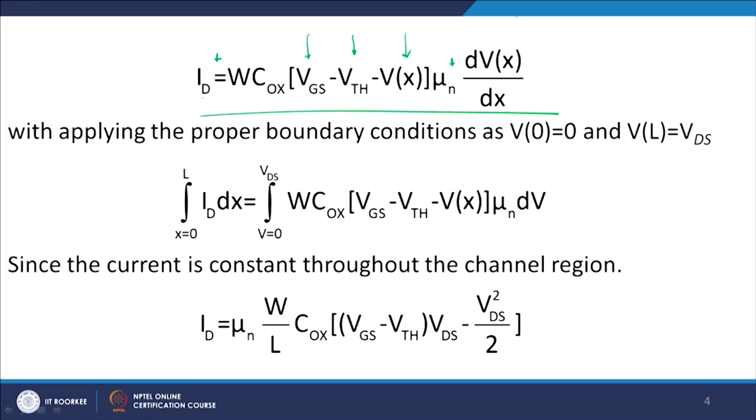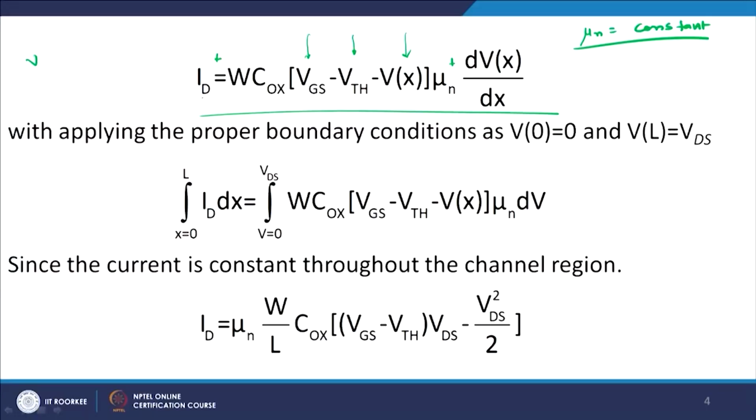Now we are assuming here for all practical purposes mobility of charge carriers to be constant. And now this is slightly over assumptions, but at this stage of your understanding, assuming mobility to be constant is the right approach to find out the current. Now as you can see from this discussion, how do you define mobility is basically a velocity per unit electric field, that is how you define mobility.